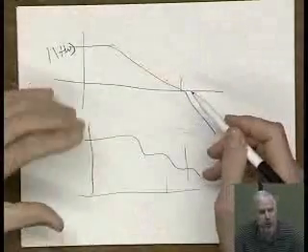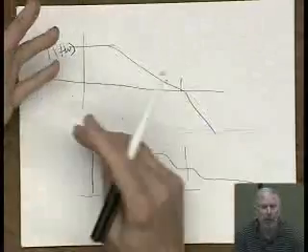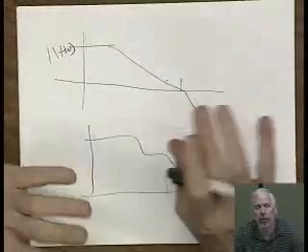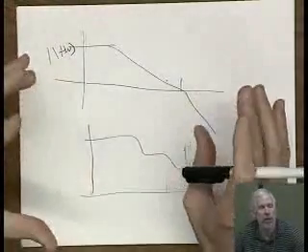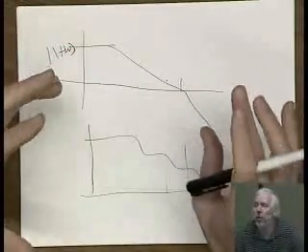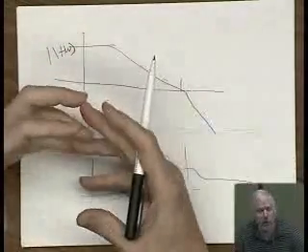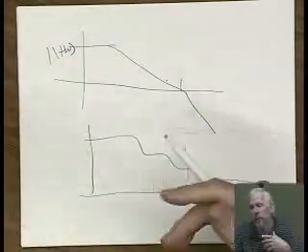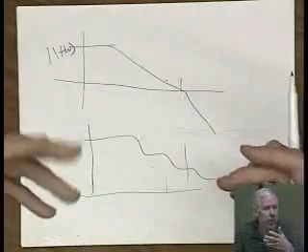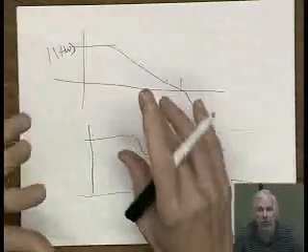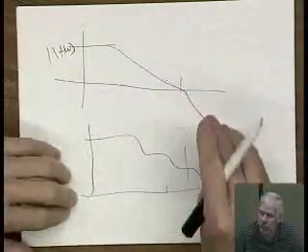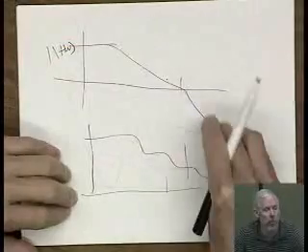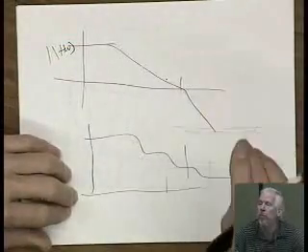Because what can happen is the circuit may be way off, working in a very strange mode. Those test benches, they're not written robustly enough to determine that you've got some real screwball stuff going on. It's going to give out a number, and it just may be a coincidence that it happens to be a good number. Okay, it may not be any good number at all. So don't rely on those test benches as a primary mechanism to see how well your circuit's working, or to calculate phase margin or anything else.